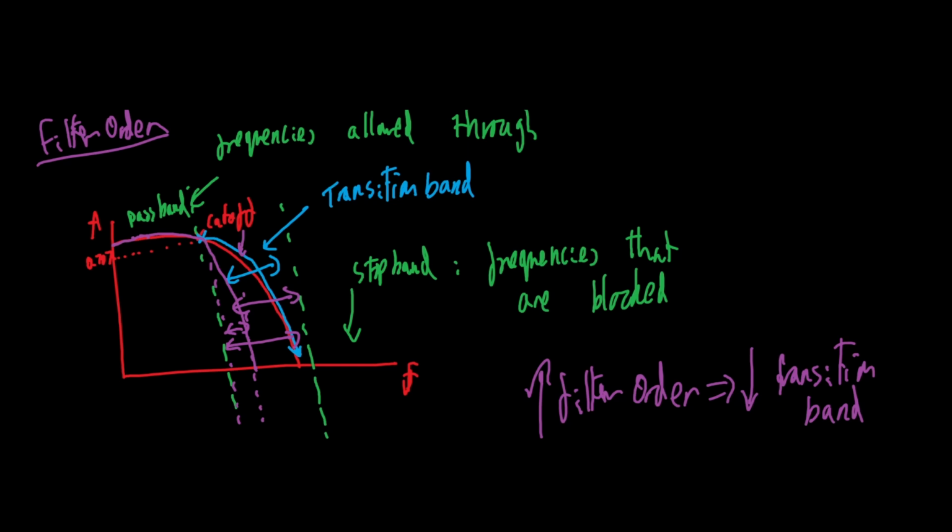Now let's look at the ideal. An ideal filter looks like this. You see, it is a rectangle. It has no transition band, and it's ideal. It doesn't exist, of course, but that is ideal, and that's what the most wanted filter would be. We know that we want a higher filter order because it's higher performance. Remember, smaller transition band is a higher performance, more selective filter.